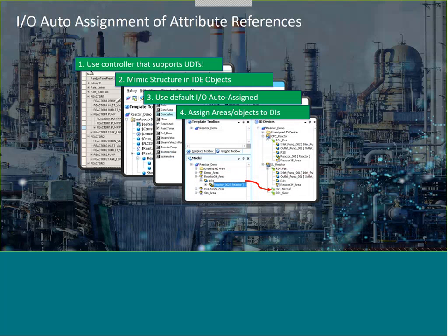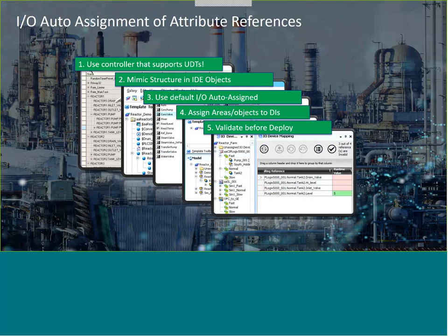So what this allows us to do is drag the objects that we've created into the topics that are linking to the PLC, and providing that those structures align, the structure inside the System Platform and the UDT structure in the PLC, they will automatically link all of the I/O for you. And you can even test that they're working in design time. So you validate them here. You can even update the resulting reference if it isn't quite right, so you can do a bulk export and import to achieve that. So they're simplifying the way that we can get the data into the system.